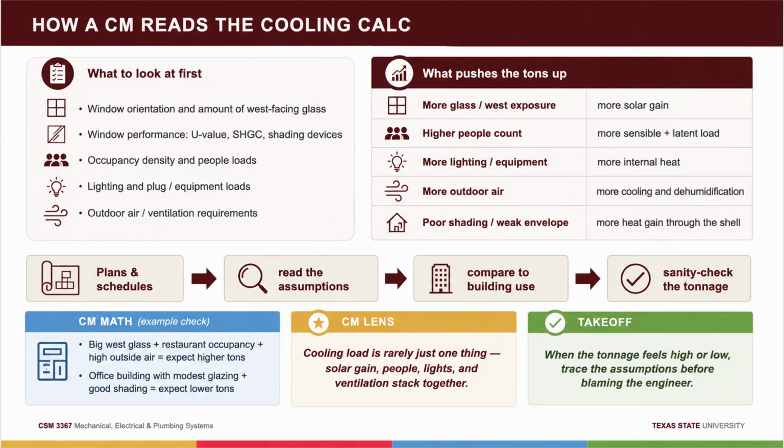And the occupants respond by cranking the set point down, chasing comfort with temperature because the machine won't give them dryness. Higher bills, worse comfort, and in bad cases you're on the road to condensation and mold. The thermostat is satisfied, the humans never are. Quiz alert. Oversized cooling equipment short cycles: rapid on-off operation that increases wear and kills dehumidification because the coil never runs long enough to remove moisture. Cold and clammy equals the signature of oversizing. Bigger is not better. This is guaranteed quiz material.